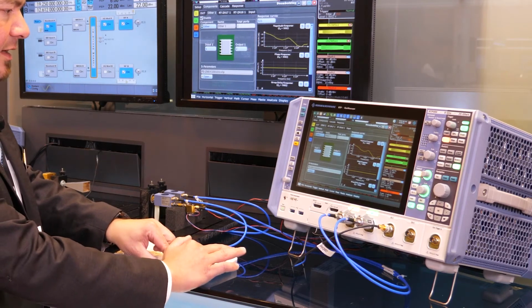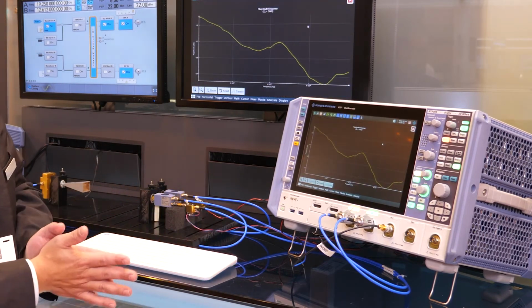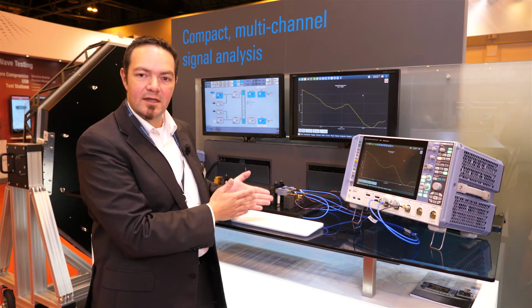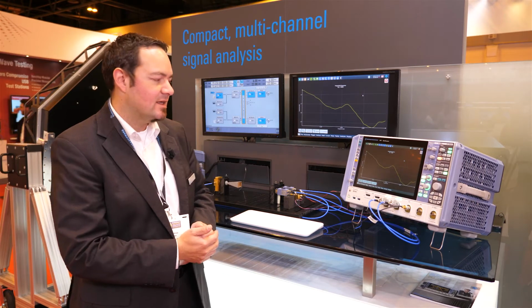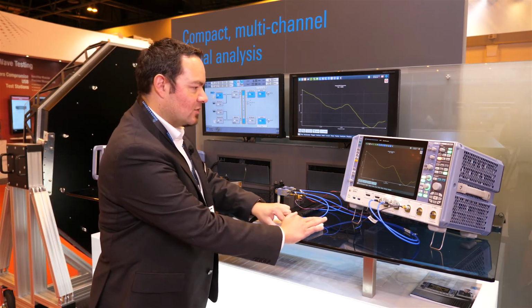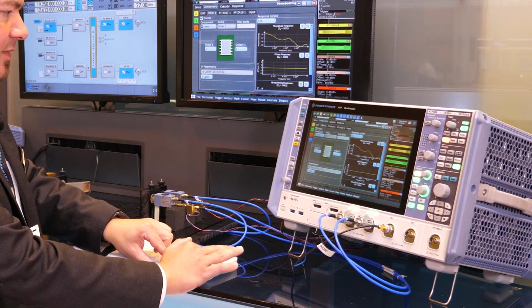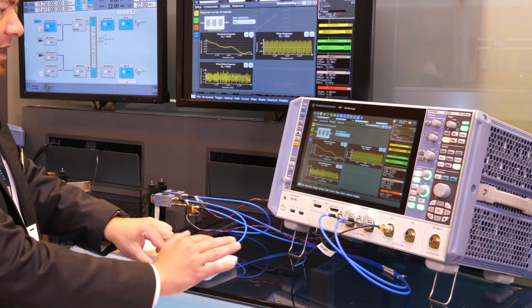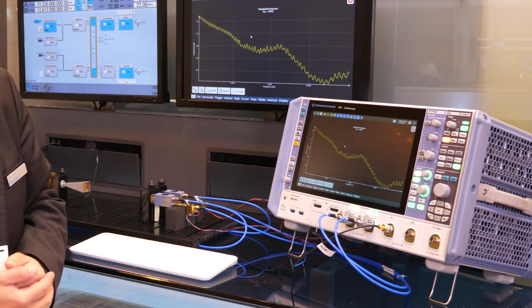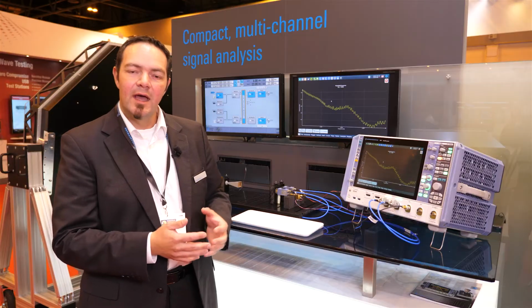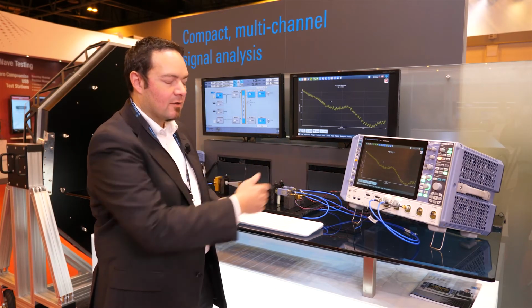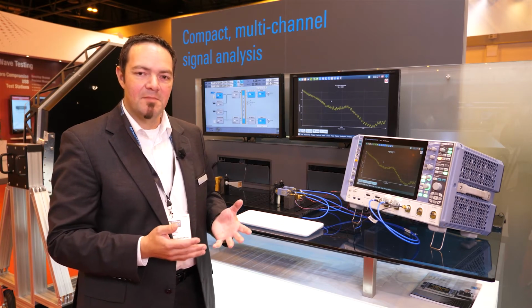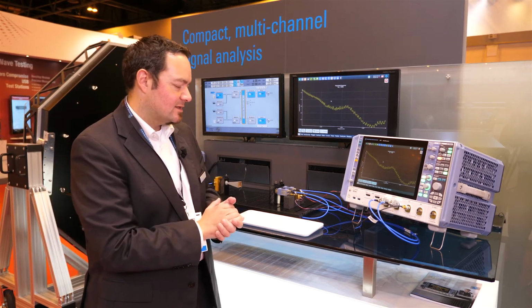So for the mixer, I have the conversion loss, and the conversion loss under this condition is ranging from -15 to -20 dB. In combination with the cables, we also see, for example here, the complete conversion loss, the magnitude response. The main driver is here the conversion loss from the mixer, but we see the ripples, they are introduced due to the mismatch of cables, adapters, and the mixers.